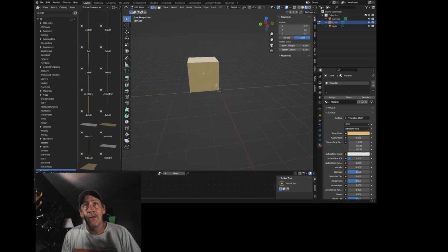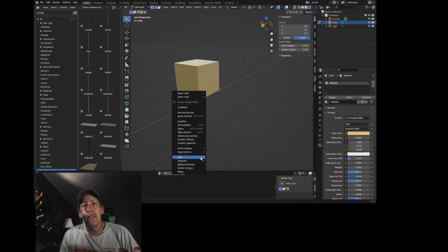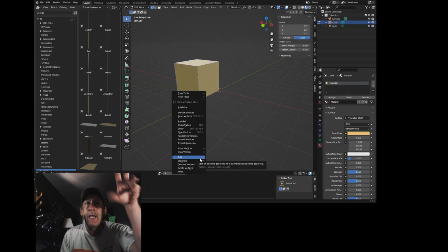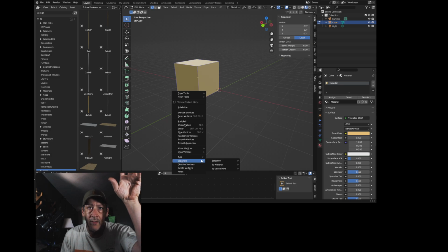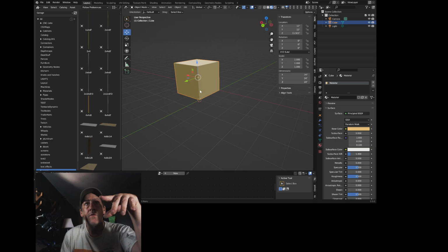Let's say we want this point to be our pivot point, to swing it open. Then we can take that point, select it, and you have to go into edit mode to move the cursor around. Then you pick your point, snap, cursor to selected. Now the cursor is over here. So if we go back to object mode, our cursor's in the corner.